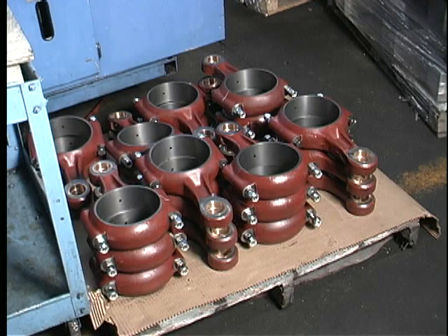You should always try to produce parts that are machined to the nominal dimension. However, the upper and lower tolerance limits will establish a range of part sizes that will be acceptable, thus preventing you from having to machine all parts to exactly the nominal value.